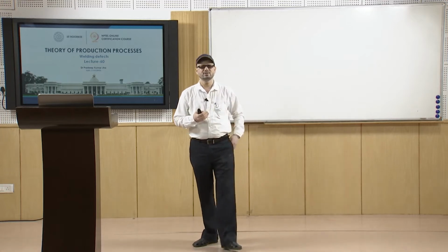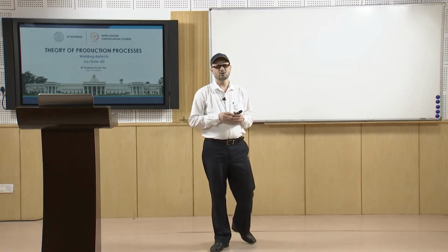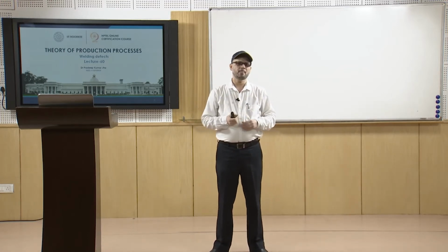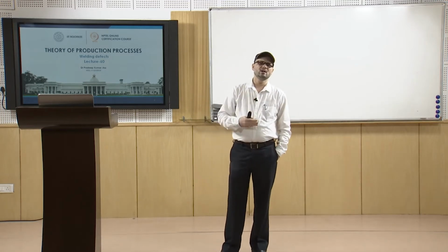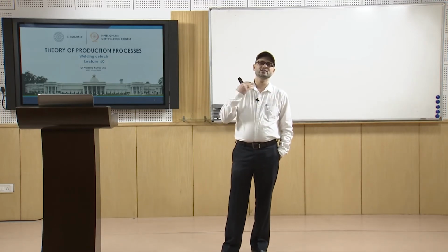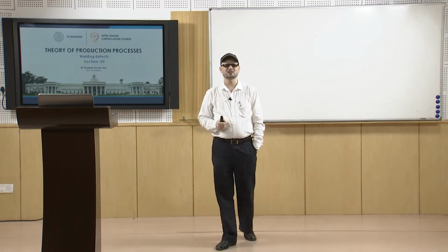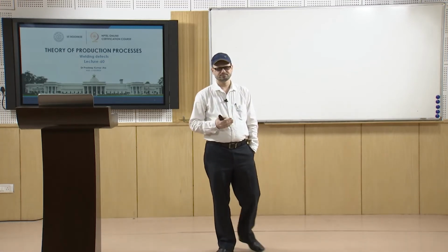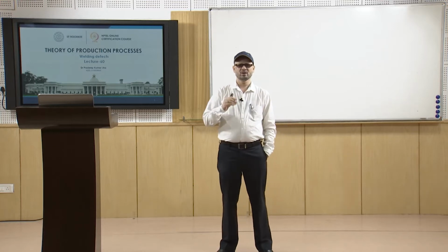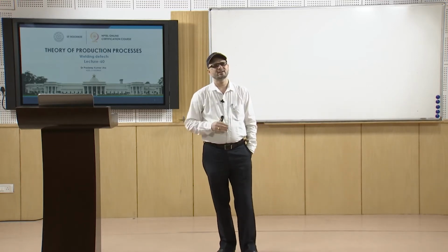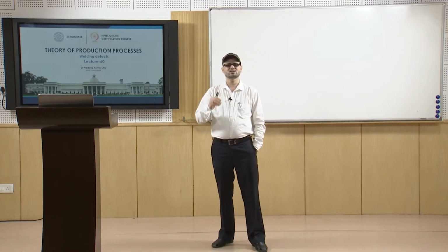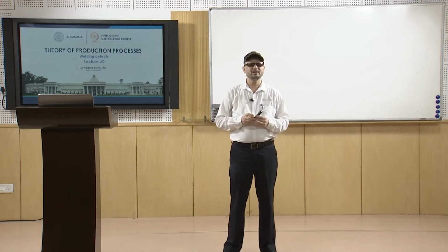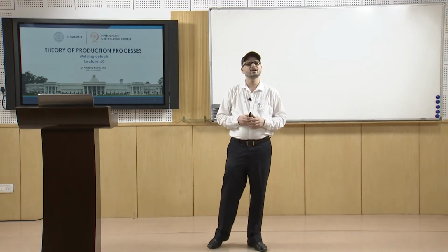Another cause is the use of substandard materials. If you have to use an electrode of a certain quality and composition, and you are not using the proper composition or proper quality, or it is not maintained in a good state, that leads to defects. Many a times with stick electrodes or coated electrodes, we need the coating to be in a dry state. If it is not kept in a proper place and in proper shape, that may lead to welding defects.